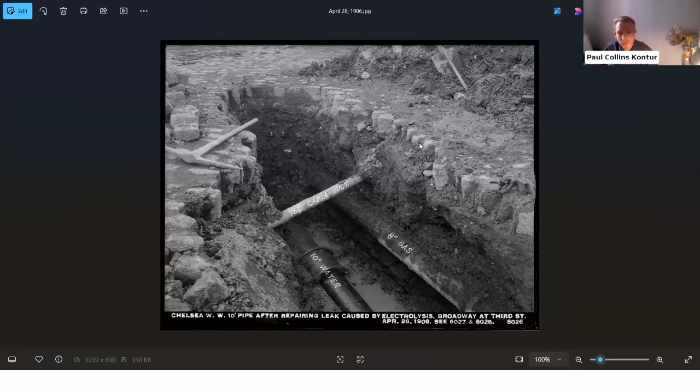Absolutely. This is also interesting. The build of the road is typically still there. It's just been overlaid in new asphalt, for instance, and you can see this in the radar data as well. That's interesting too, because if you're going to excavate, typically you have to put back what you find, right? If you install something new, you're responsible for that reinstatement, and maybe that reinstatement fails in X number of years.